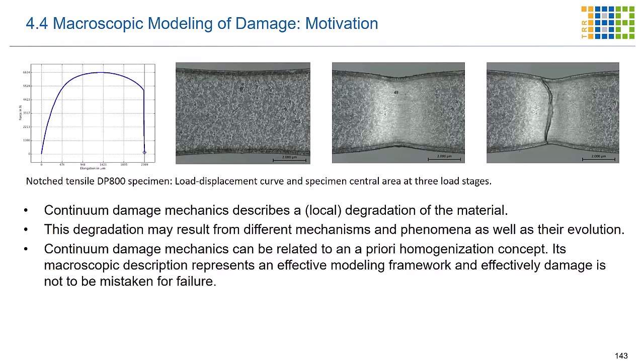Rather, the effect of the underlying microstructure on the material response is modeled. What can these different microstructural features be? One can think of voids, grains, grain boundaries, inclusions, microcracks, and all the others. And in these approaches, different damage mechanisms such as microcracks, cracks along grain boundaries, growth of voids, rupture, and decohesion are cumulatively taken into account.